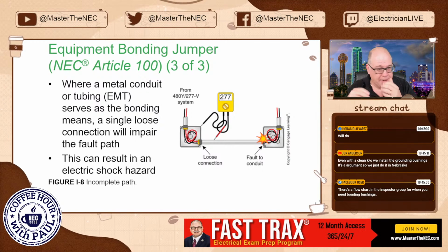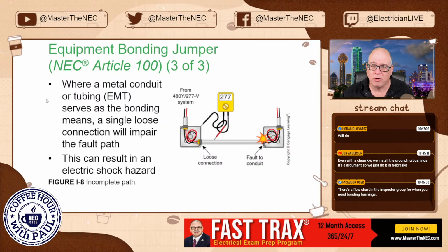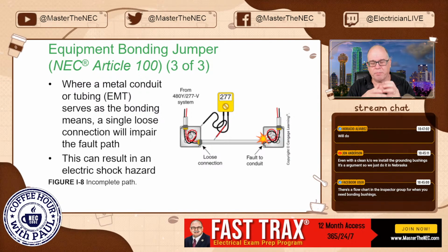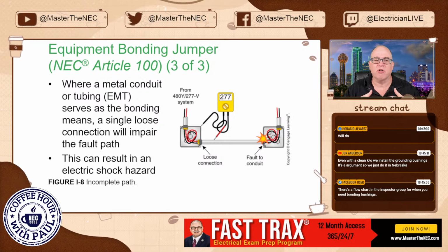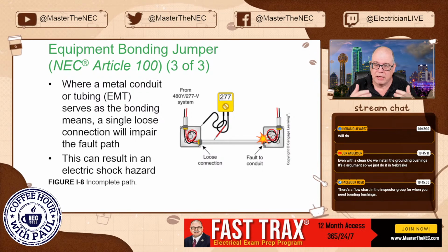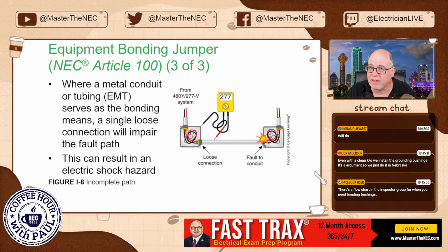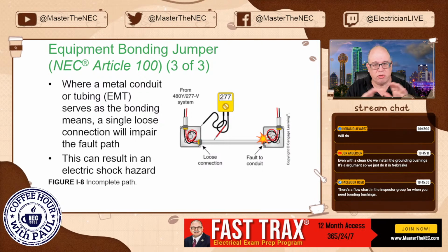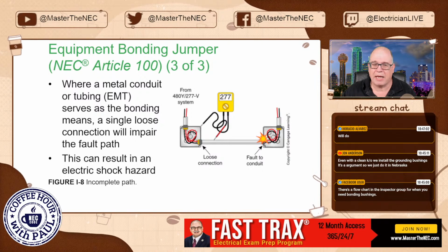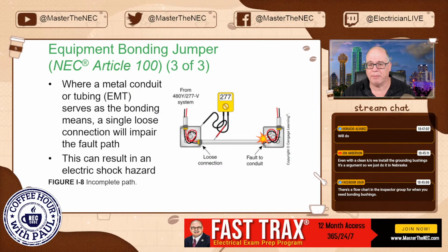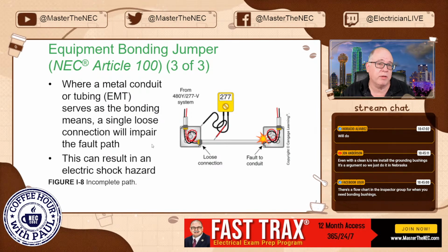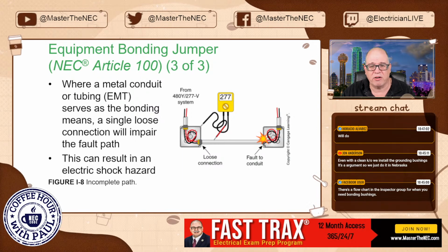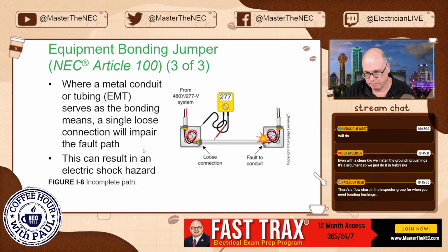So at the end of the day, a lot of engineers just want the wire because they feel better about it. In fact, on a rooftop for HVAC, if you're using compression type fittings and things like that, which is outside in a wet location, then you're required to run a wire type equipment ground in there because of vibration and movement. But again, everybody does what they want, but a lot of people, that's the reason why they put the wire type in there. So I don't have anything wrong with using the raceways and things like that. I'm just telling you why a lot of engineers and designers want the equipment ground in there, okay?